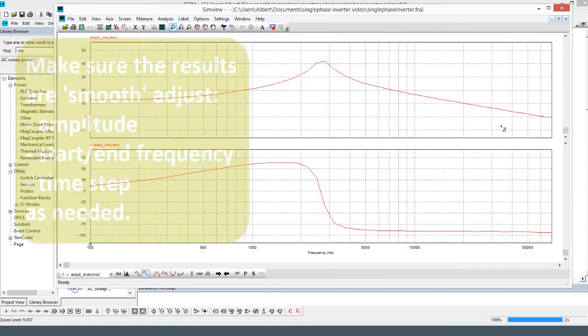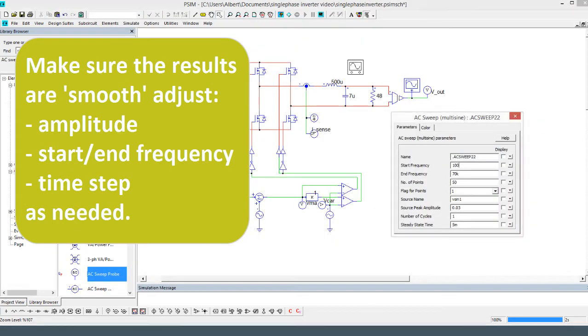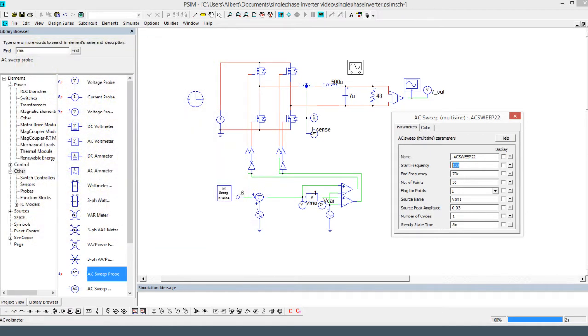And this looks pretty good still. Yeah, we're stabilized in the phase. Our amplitude is going down still, and because we need some lower frequency points, I'm going to drop this number down to a lower frequency, and we'll bump up the points again to make sure we get nice resolution on the resonance peak. We'll run it, and this will take maybe 20 seconds. So we'll pause the video right now, and we'll come back when the simulation's done.